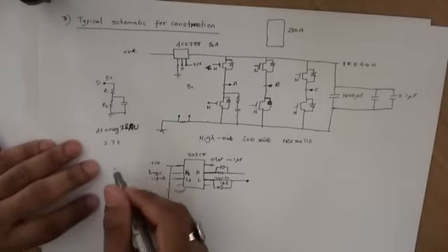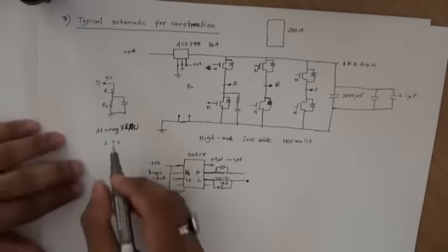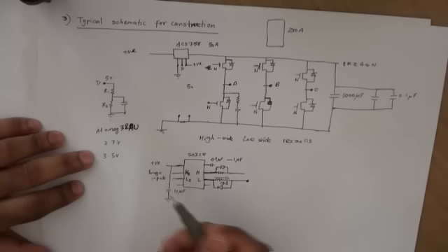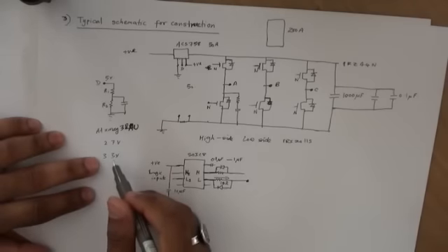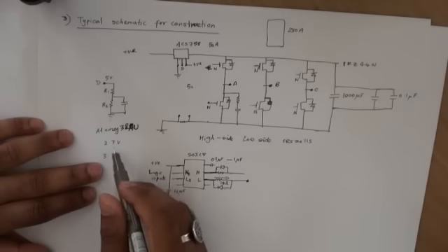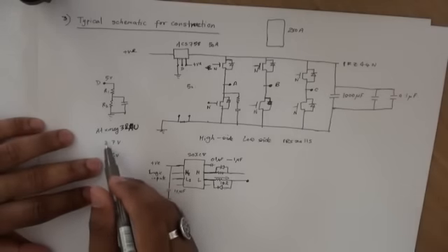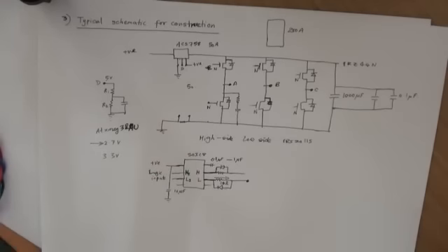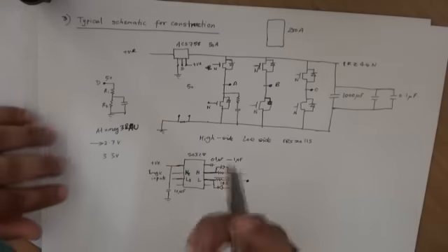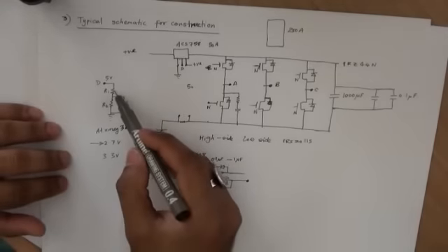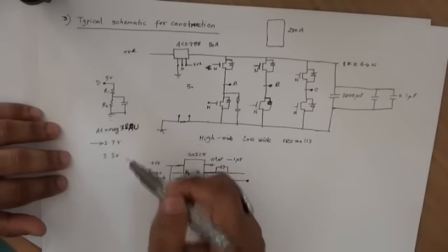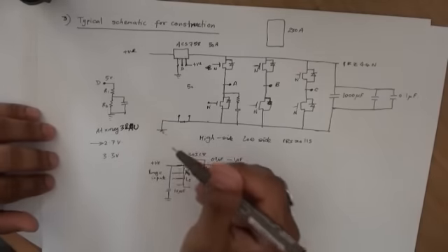Unfortunately, even though the microcontroller operates up to 3.3 volt, the ADC does not accept up to 3.3 volt. It's actually 0.6 volt less than that. So 2.7 is the maximum you can use for the ADC level. So you have to make sure you use a reasonable voltage division here in order to obtain the level that the microcontroller can handle.